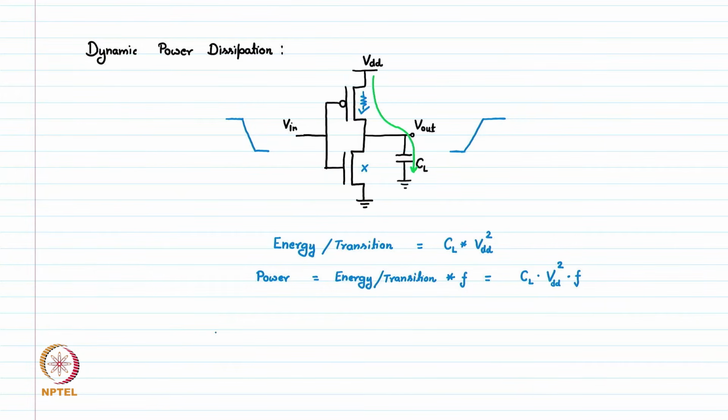So if we see closely this formula, we can deduce that this is not a function of transistor sizes. So this does not depend on the size of PMOS and NMOS.